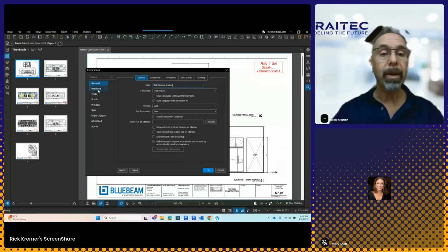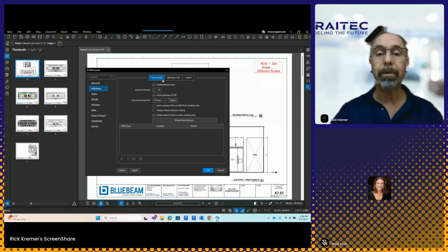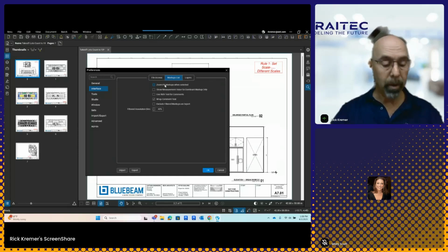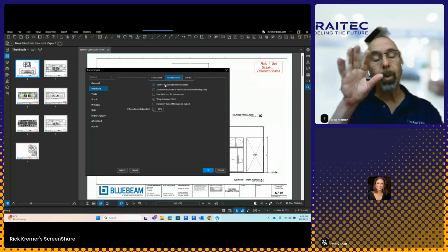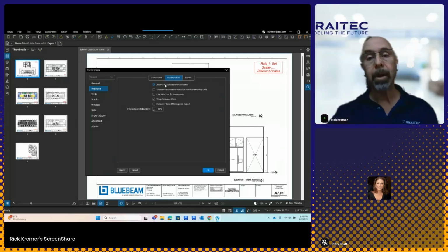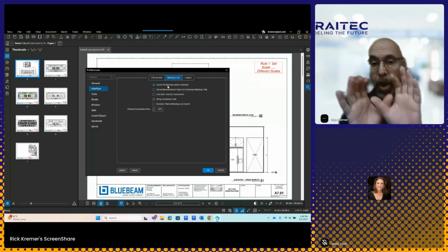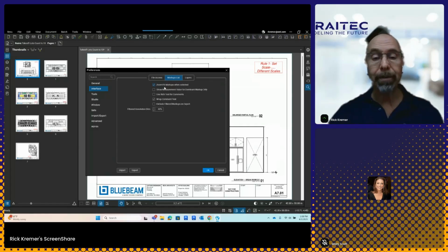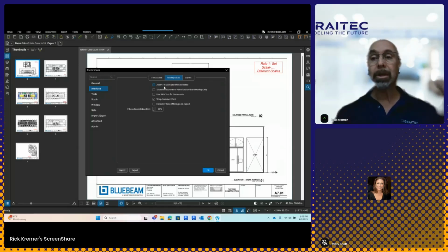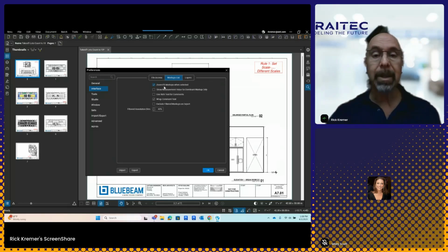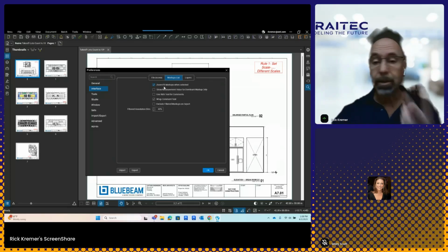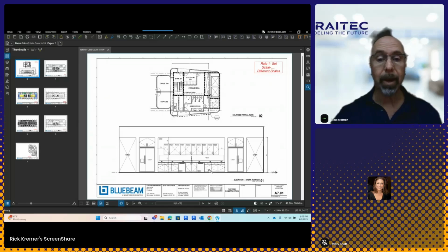Second, over here under the interface markups list, you want to go through and change zoom fit markups when selected. This is just general 101 settings that I like to do. And what this means is as you click on a markup in the markups list, it'll automatically zoom to the markup on that sheet. With this unchecked, the way it is out of the box, it just goes to the sheet itself. And it's hard to find, well, where in the heck is that particular markup? With this selected, it goes right to that markup. That's it, folks, just two things. Let's go ahead and hit OK.